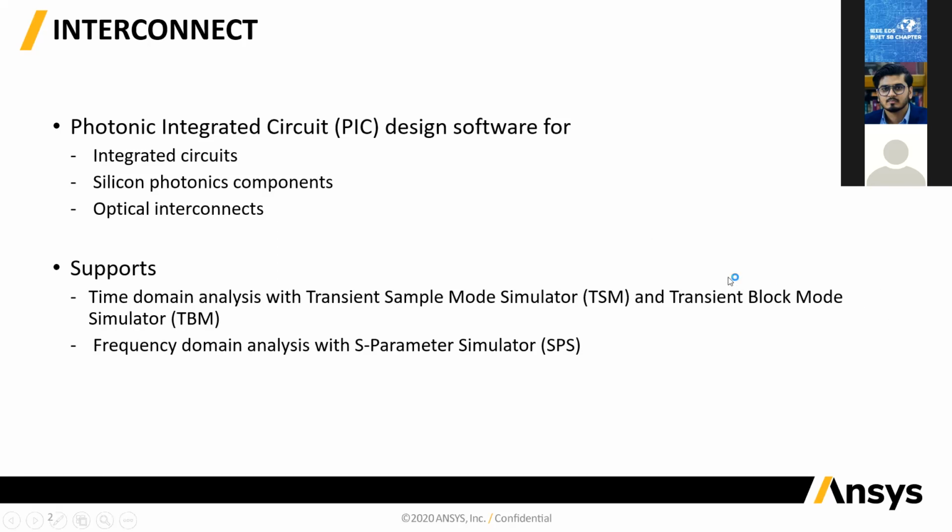Frequency domain simulations are usually much simpler and can be run quickly to just figure out the idealistic behavior of your system. And then you can do time domain simulations, which usually are more time consuming and complex, but also allow you to perform signal integrity analysis for your system, so you get more important information about the performance of your system.